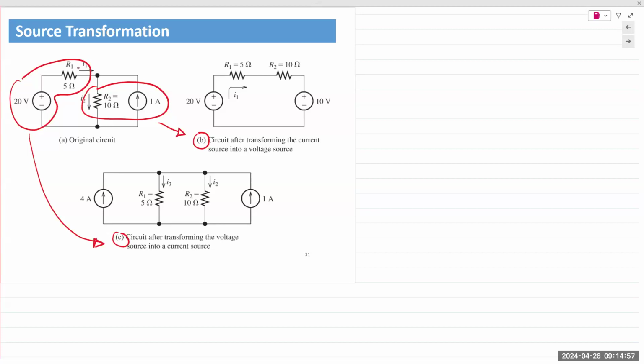What we would do is we would break up the circuit right here in the middle. You have to break it up at the point where the voltage source and the resistor are connected. Okay, so if I break up the circuit, it would look like this. I would have a voltage source, I would have a series resistor. I would mark those nodes in the original circuit, A and B.